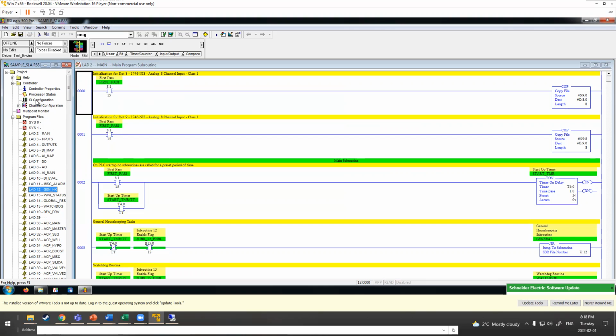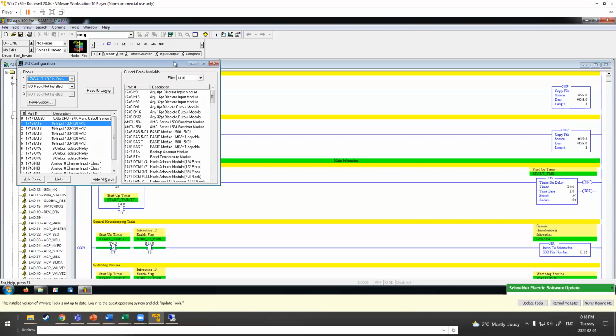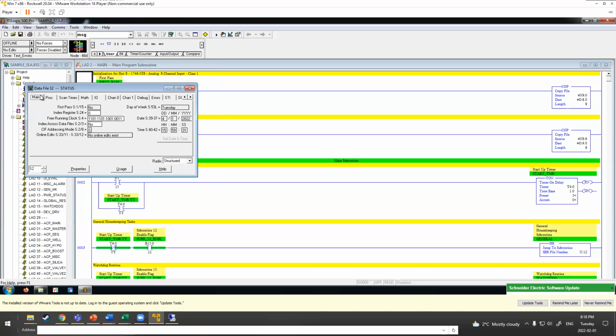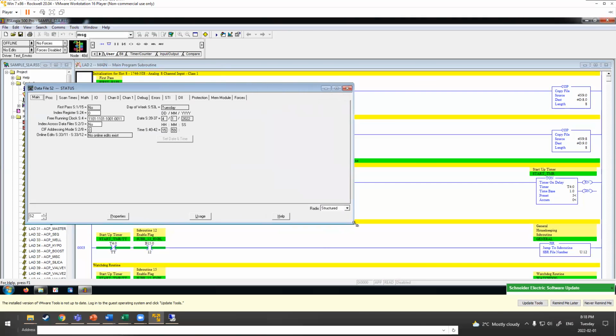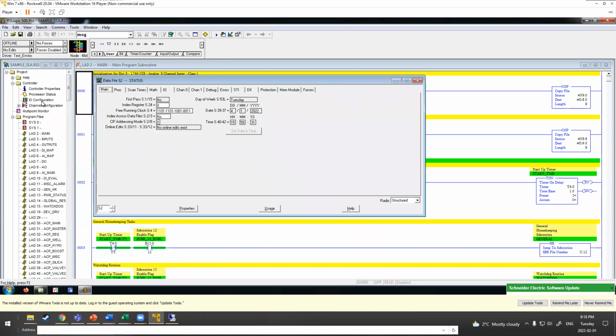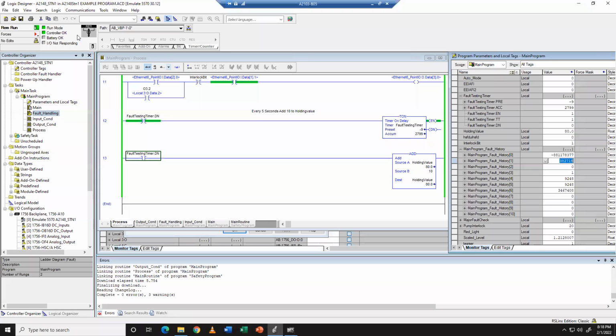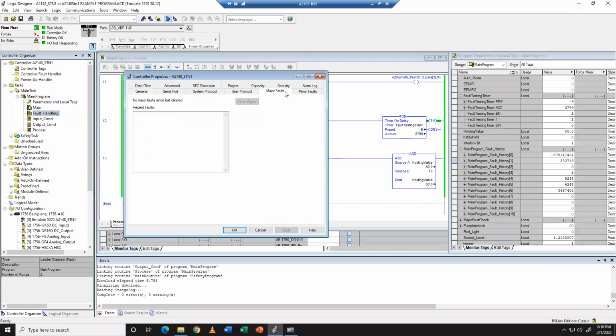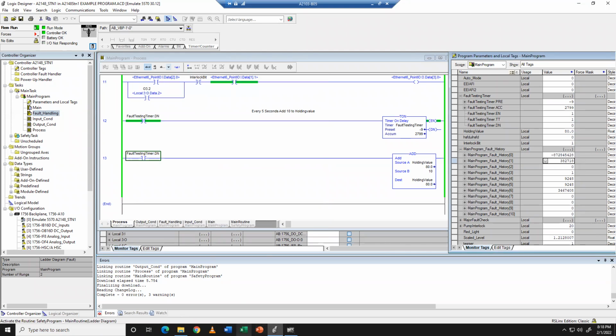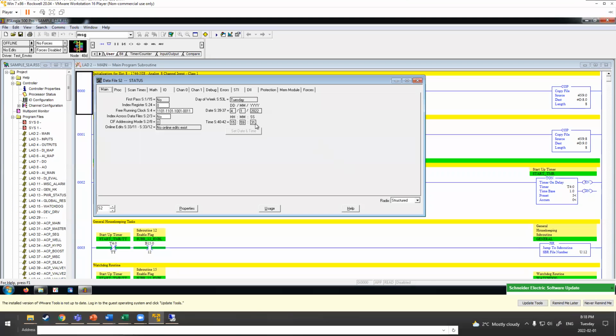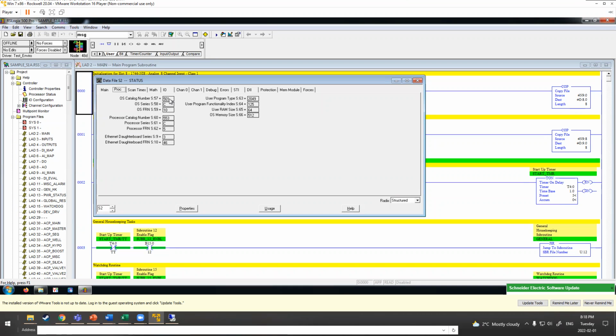So you don't need to do any fancy messaging to extract system values. You can actually pull them right out of statuses. So when you're in the 500 environment, you've got the processor statuses. It's similar, not identical information that you can get from some of this for fault information and configuration, but you can get your date, time, you can get firmware statuses, so you can know how much RAM is available, how much memory is available.